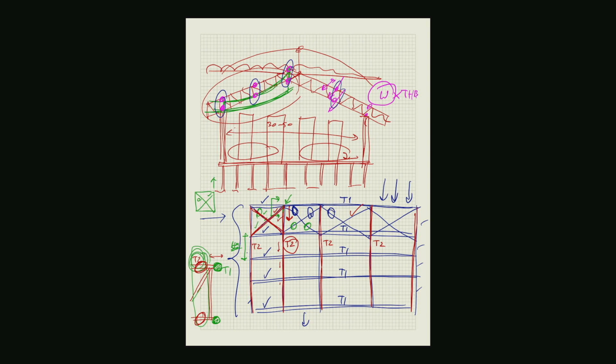So you run the buckling analysis. You apply the distributed force on the roof truss, and you run the buckling analysis. You'll be able to get the buckling load and see if it is enough for your purpose or not. If your W, which is uniformly applied over the truss, is not enough, then you can look at which particular component is suffering from the buckling, and then you look at that and try to fix it. So just keep fixing it.